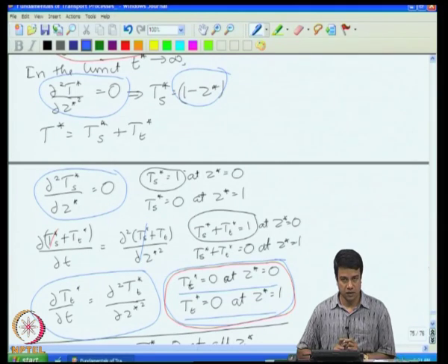So, therefore, the transient part of the temperature is the correction to the temperature profile for t being of order 1 or small. In the limit of t being large, this will go to 0. So, having separated the temperature into a steady and the transient part, we have to separate the equations also into individual equations for the steady and the transient part.